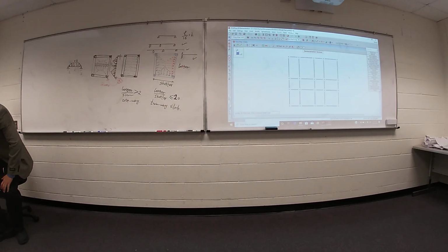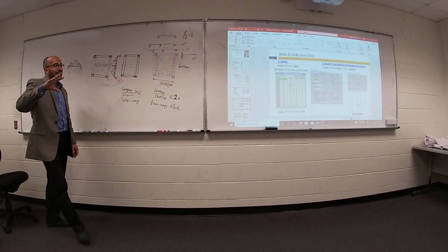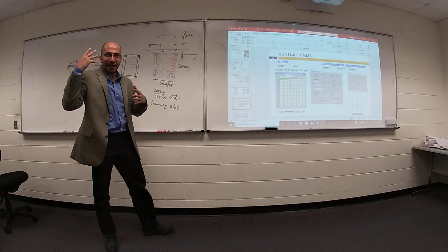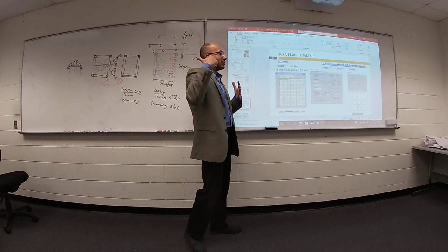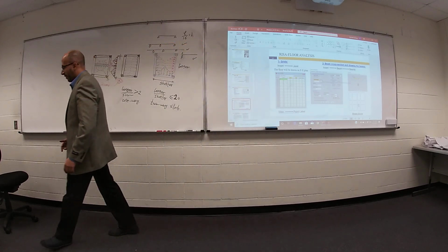Anyway, for beam cross section and drawing: insert, beams. Then from this option, open this icon to define your cross section and then draw your beam. Any question? I know this time is different, not like the first time you learned how to use RISA 2D. It's completely different. You have a good background about RISA, so just know what is new in these commands.